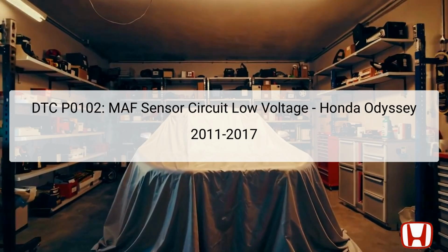This particular sensor is usually located near the air intake or air filter box in your Honda Odyssey. A low voltage reading could lead to poor engine performance and increased emissions. The PCM relies on accurate MAF readings to help in effective fuel injection and ignition timing. Thus, addressing this diagnostic trouble code (DTC) is essential for maintaining the vehicle's performance and compliance with emission regulations.